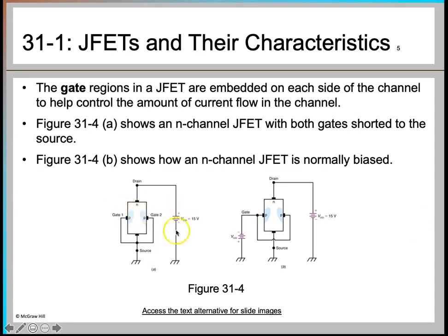You understand? So when you increase this VDD or VDS to a level that these two regions appear to touch each other, that condition is called your pinch off, and the voltage corresponding to that point is called your pinch off voltage. And the word pinch off came from a pinch, which means gripping the object,